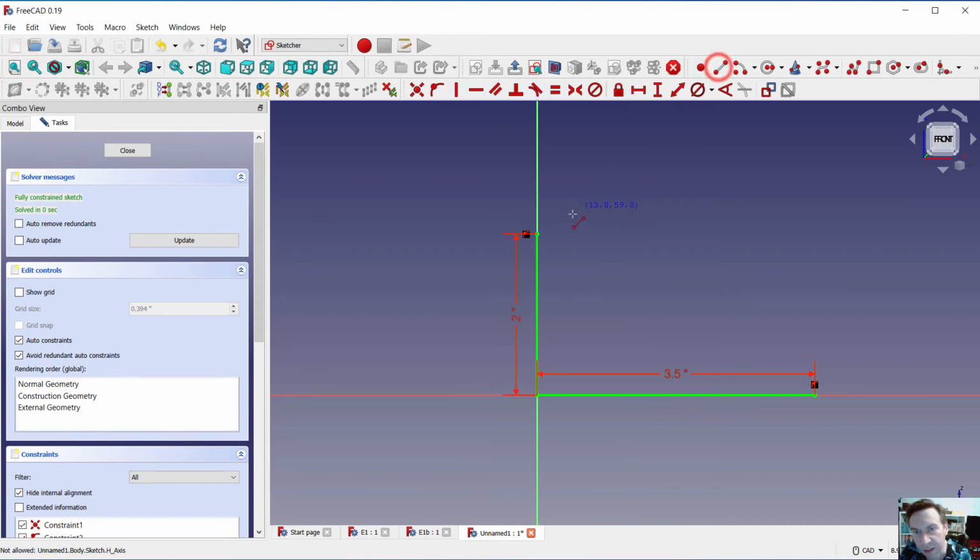Let's go back to line there, and then across here, and the next one is 1 inch across. And in this case, I noticed I'm having a difficult time. There it is, horizontal. You have to look for the little symbol to the right of the pointer with the horizontal line to indicate an automatic relation. So click,